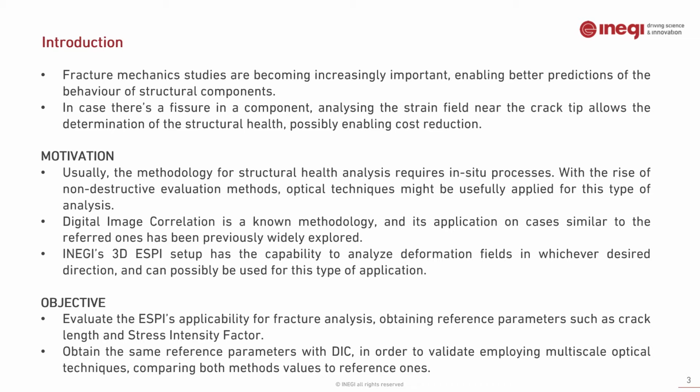The motivation for this work falls precisely in fracture mechanics' increasing interest. Most methods that allow structural health analysis are in situ. With the rise of non-destructive evaluation methods, the applicability of optical methods was considered. DIC is an already established method, but ESPI is rarely used for this type of application. INEGI's 3D ESPI setup was an appropriate system to study the capabilities of this type of methodology. As such, the objectives of this work are studying the applicability of the ESPI system for fracture analysis and then comparing it to the DIC technique and other reference values.